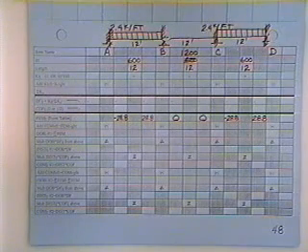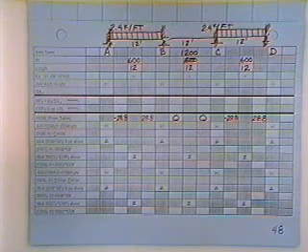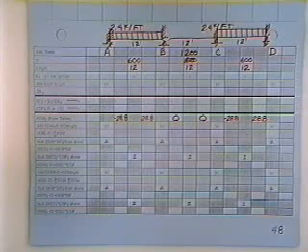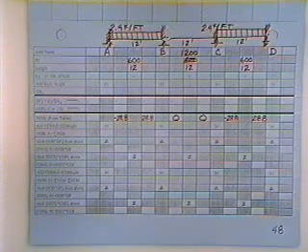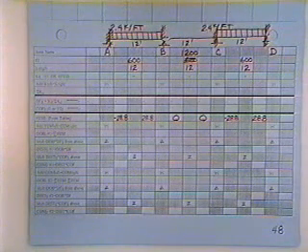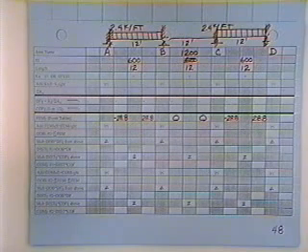On page 44, it says, how do I compute K sub ij? How do I compute K sub AB, for example? Well, the stiffness of any member is 3EI over L. 3 is a constant, E is the modulus of elasticity. I've already got EI and I've already got L, so that's nice. They're already in the table. I just multiply 3 times EI over L. If, when you stand at that joint and look at the other end, it's pinned, it's 3EI over L.